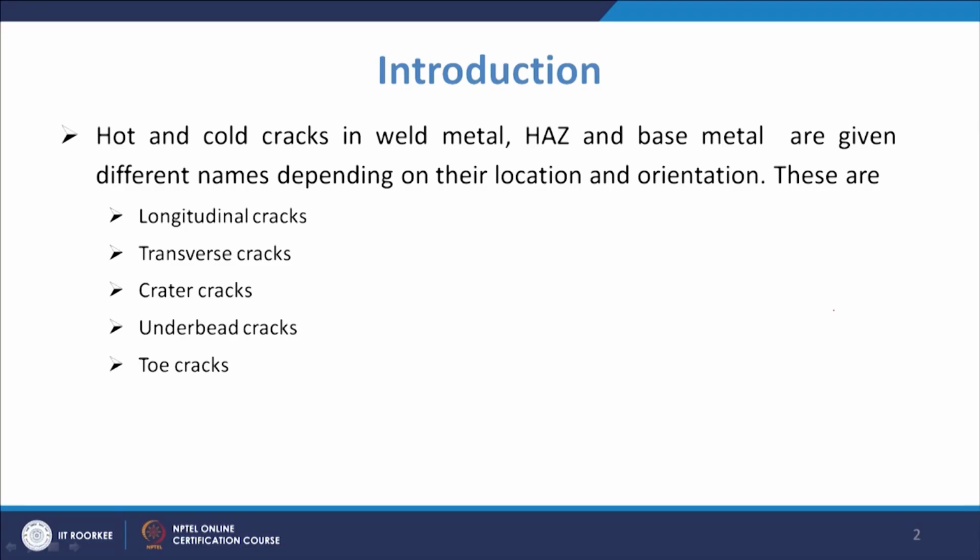You have the longitudinal cracks or transverse cracks, then the crater cracks or underbead cracks, and also toe cracks. Longitudinal and transverse depend on how they are oriented. Crater cracks are named because of the crater position, and underbead and toe cracks because of their location. We will talk about these cracks in more detail in this lecture.